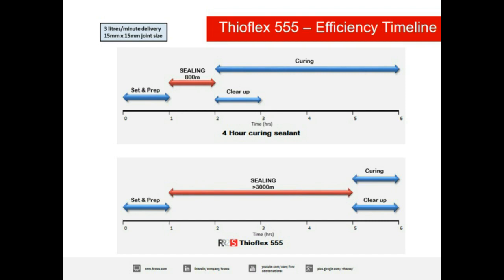So let's look below. Same setup procedure, about an hour to get set up. Based on that 15 by 15 mil joint, remember, we can then apply upwards of 3,000 linear metres in the same 6-hour period, with just 1 hour, based on about 15 degrees, for curing time encompassing our cleanup. So 3,000 metres in 6 hours. A huge uplift in terms of efficiency and work rate.